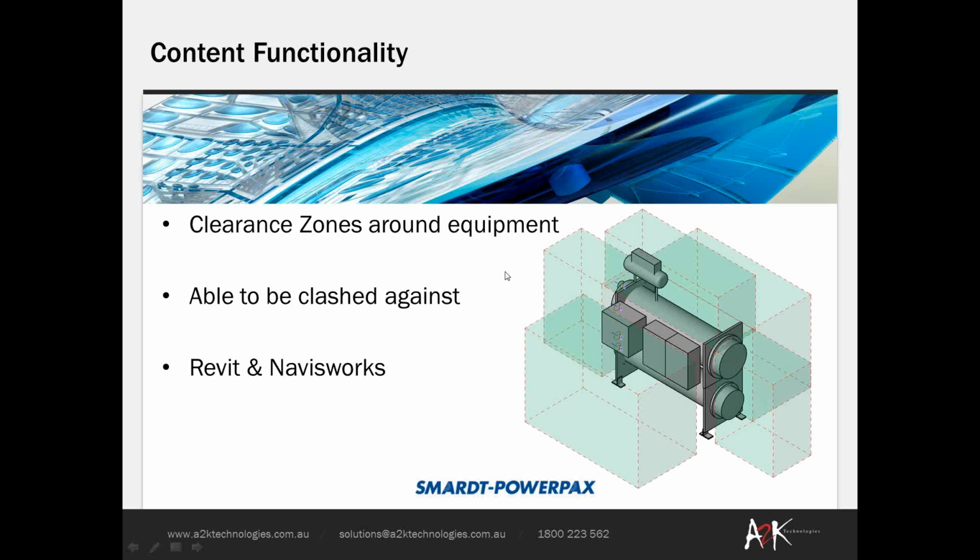So you can see straight away if there's not only a clash with the equipment itself, but if there's a clash with external elements coming into the clear zones of this equipment, and you can say, right, well, there's pipe work too low here, or there's a bit of ductwork coming in and clashing where it should be clear, or the head height's not right for the clearance zone that's needed for this piece of equipment. Okay, so that can be quite useful.